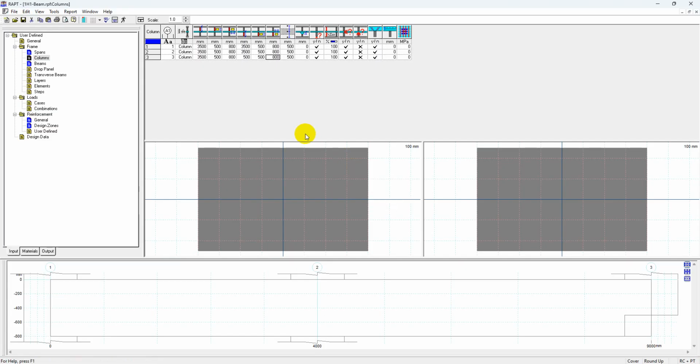So how do we know whether the beam is connected to the strong or to the weak axis? We need to inspect first. Make sure that the input values here and here will result in correct column framing to the beam.